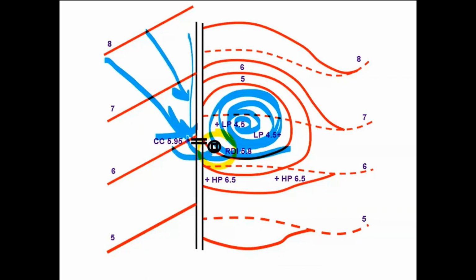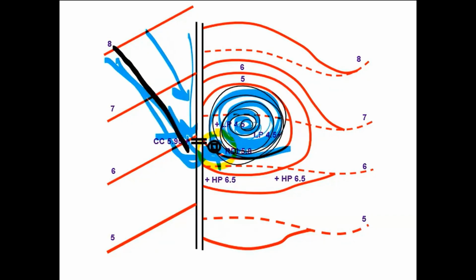It's going to run in, and the least path of resistance is going to be right into that raised drop inlet. The idea then, of course, is that we're assuming that it's dirty water that's going to be in the bioretention area here. And then once that fills up with dirty water, the clean water is going to go down into the raised drop inlet.